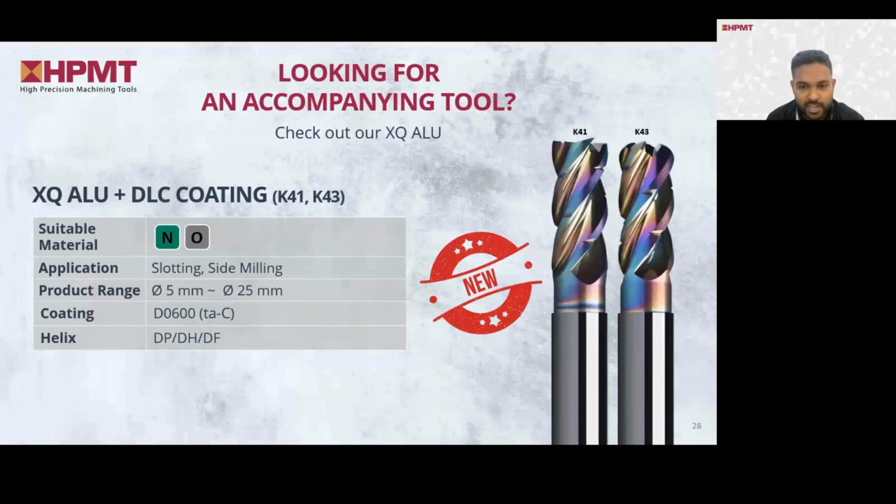The new DLC coating has significantly enhanced the cutting performance of the tool. With the addition of the DLC coating, we observed improved tool wear resistance and enhanced thermal stability. This increases the machining performance as well as productivity at your workplace. Now, the XQ Alu with the DLC coating is particularly well suited for softer materials in the ISO class, for example aluminum, copper, brass, essentially the non-ferrous materials.